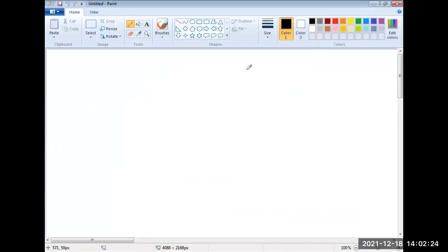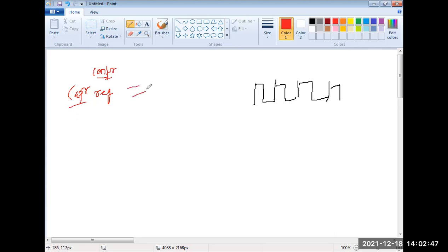When the time scale is going on, the clock pulses are coming like this, and I want to capture a certain timing interval from that. So we have capture registers in the timer. In the capture control register, if I have stored a certain value, for example 100 nanoseconds, then when the clock signal is going and exactly reaches 100 nanoseconds, it captures that value. That is the meaning of capture registers.